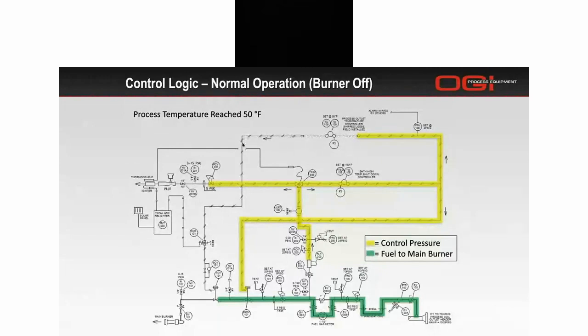So you can see now there's no control pressure going to this temperature control valve. So the speed control is going to allow free flow in the closing direction. So it's going to snap shut. When it comes back on, it's going to restrict flow and then allow kind of a slow on, just like we talked about. So if everything's going well, you'll cycle between the previous slide and this slide, on, off, heater meeting demand, call for heat, and the cycle continues.